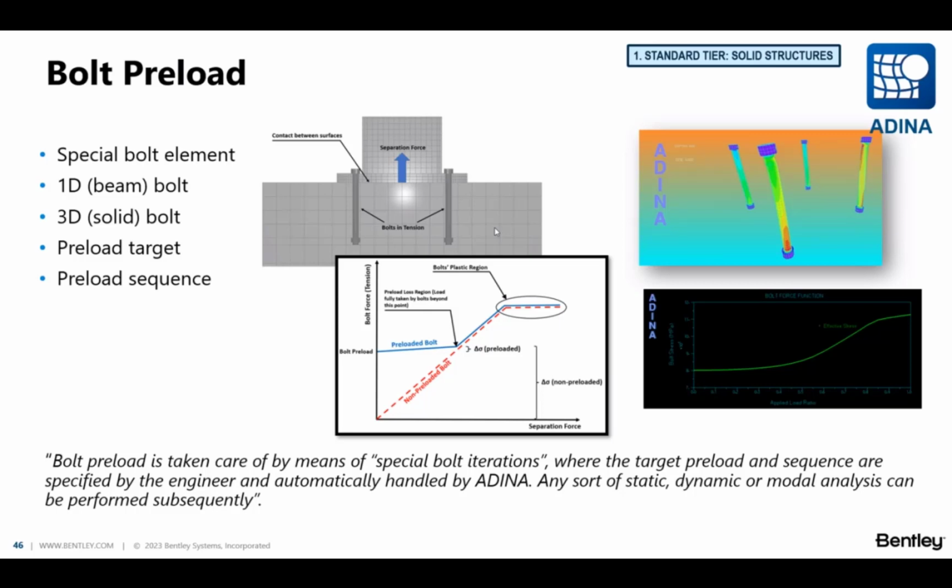And to do that, we certainly need contact between surfaces and the bolt preload feature. Ultimately, we create a bolt force function like the one you see to the right, and that will allow us to inform fatigue design of bolts and rods.